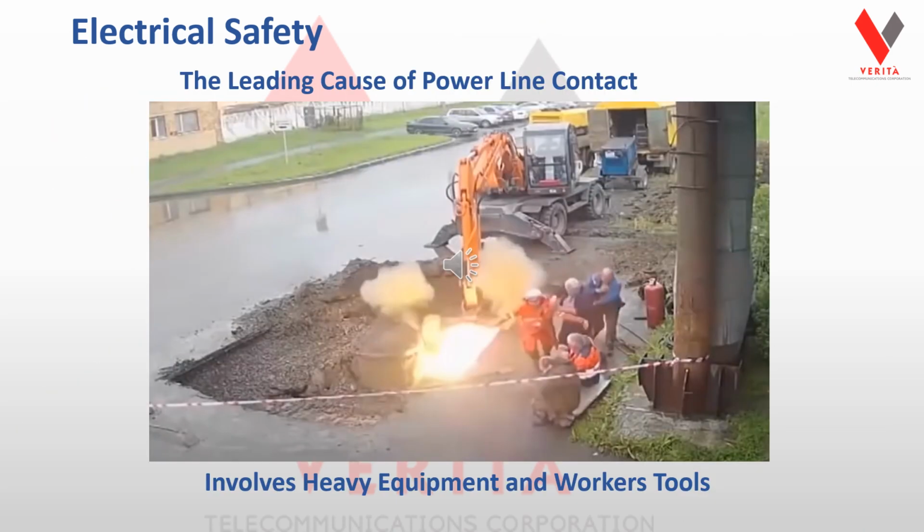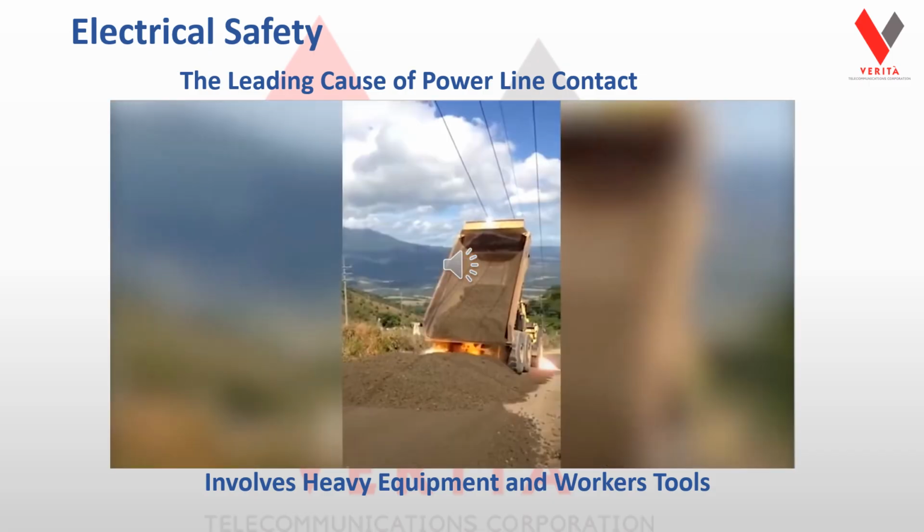The leading cause of power line contact involves heavy equipment and workers' tools. On the job site, we need to make sure that we have proper clearance for our equipment, whether it's an excavator or a bucket truck. We always try to maintain at least 24 inches of clearance.